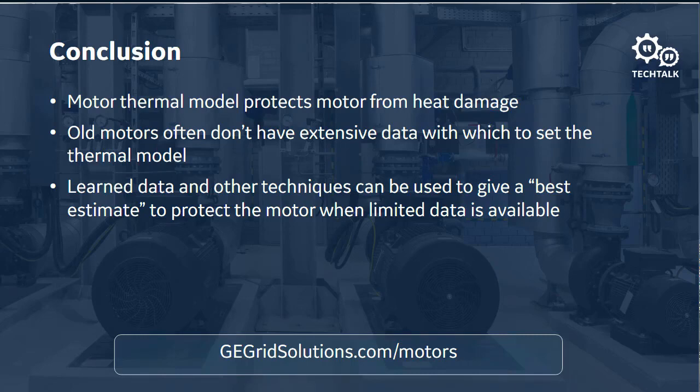But I would assume that the service factor in that case is that you have no capability to overload the motor, so you should set it to 1. That's probably what I would do. I would set it to 1 simply because in the absence of better data, I would want to be conservative.